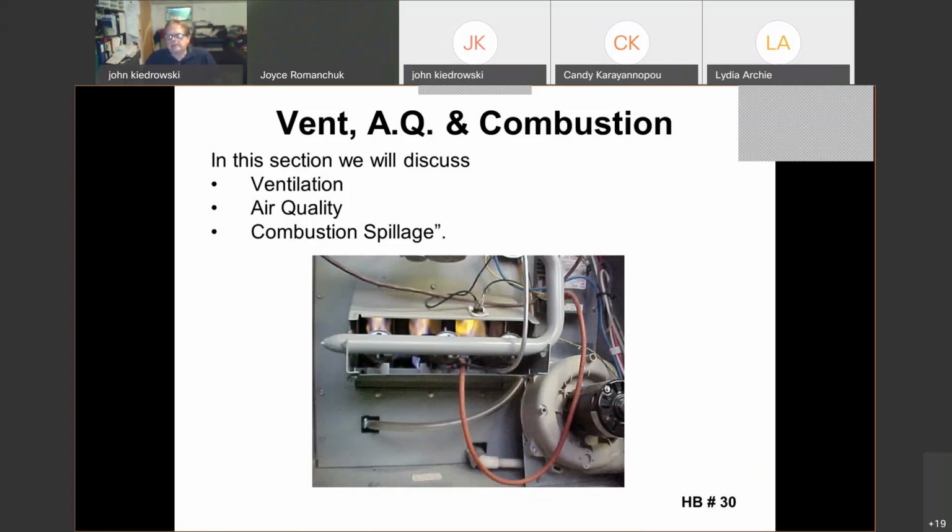To me, that's a furnace that needs to be basically looked at by a professional licensed heating contractor, because that is going to show me signs that there's going to be issues with potentially carbon monoxide and or dirty fuel jets on this furnace, which could cause problems for the indoor air quality of a house.